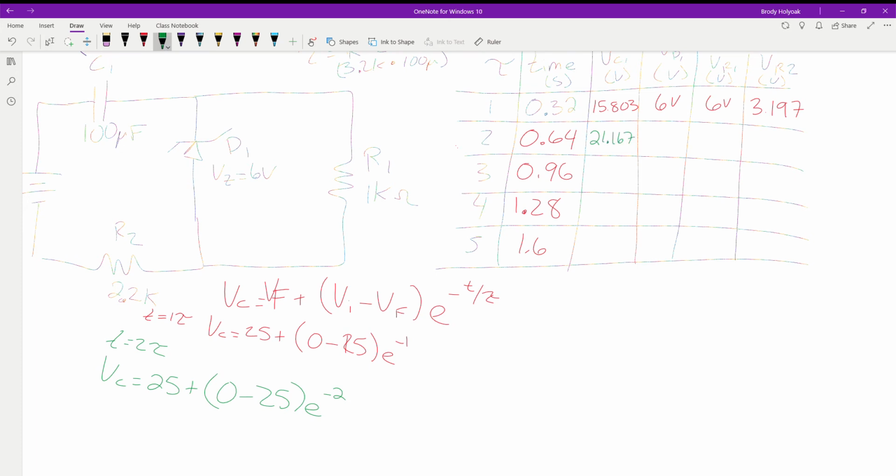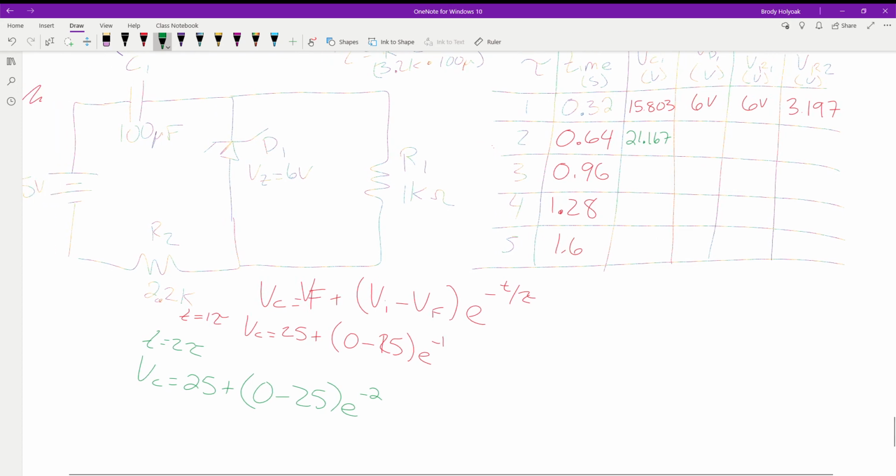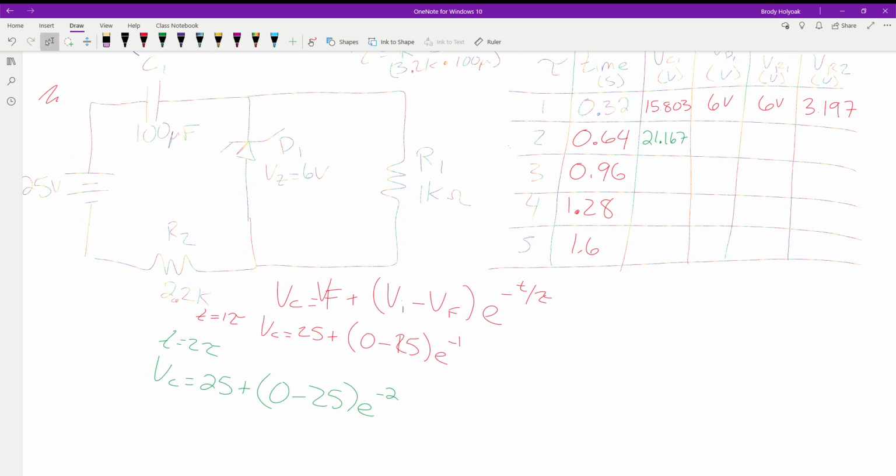Okay? How much do we have left over? 3.383. So if we have 3.383 volts, how much is being dropped across the diode? All of that. So R1 is dropping that. How much is left to drop across R2? 0.